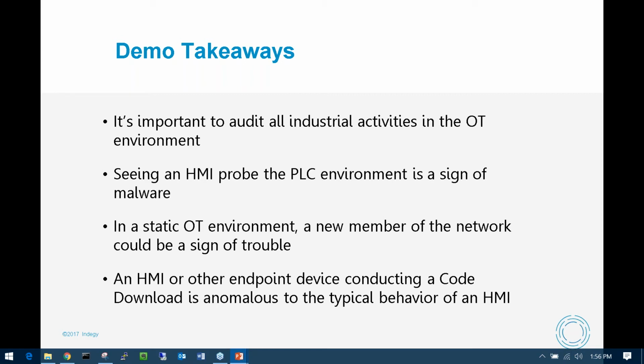Maybe it's malware, maybe it's someone that broke into the plant, or maybe it is somebody who accidentally loaded the wrong project onto the PLC. It could be any kind of a use case that we would want to refer back to an audit trail of everything that's happened and where it came from and what the impact of those actions were. Also, being able to look out for certain types of activities that indicate a breach or any kind of malware or bad activity, things like HMIs poking around, doing things that they shouldn't be.